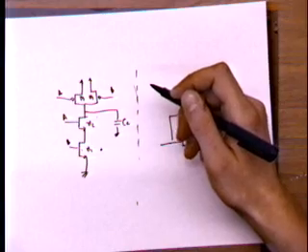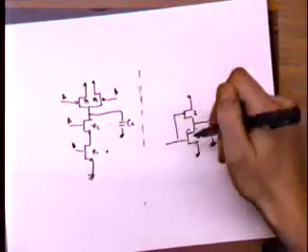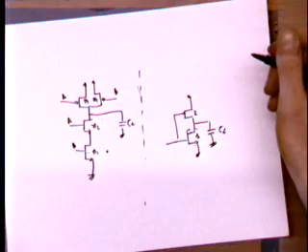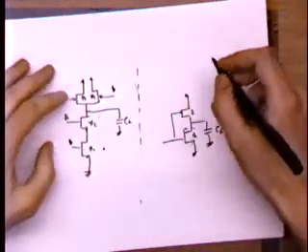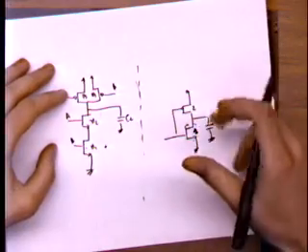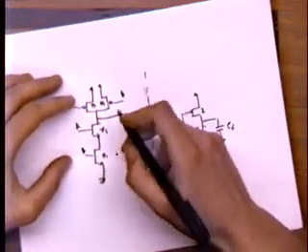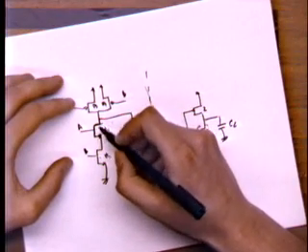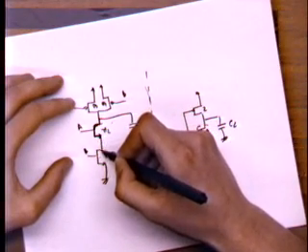Okay, anyone has an idea of how you would size this gate? All right, so we said that the delay has to be the same, right, in the worst case. And we said that in the worst case, the pull down resistance is the series of these two resistors.